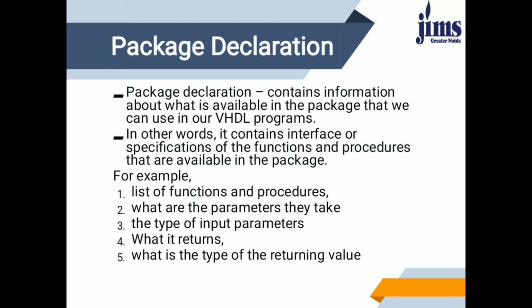So, what is a package declaration? It contains information about what is available in the package that we can use in our VHDL program. In other words, it contains the interface or specification of the functions and procedures that are available in the package. For example, what it returns, the type of input parameter, the type of returning value, what parameters they take, and the list of functions and procedures.